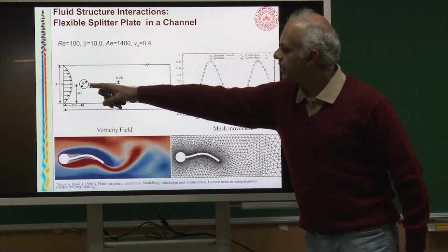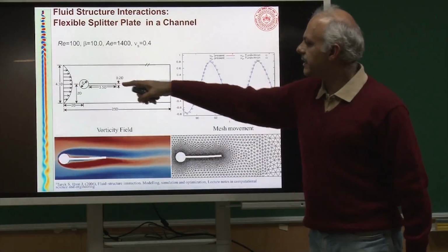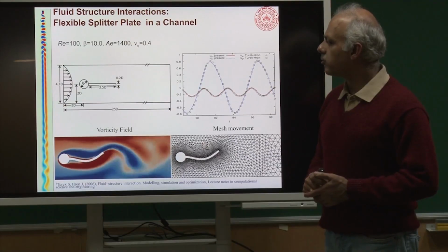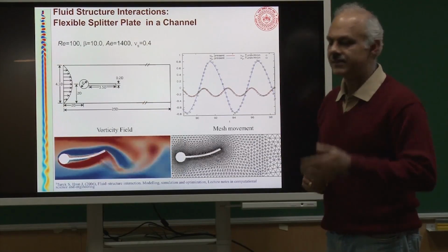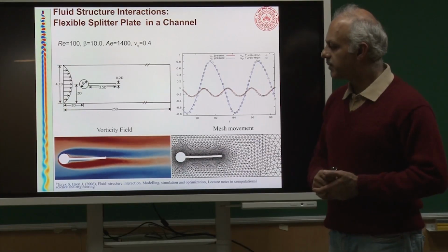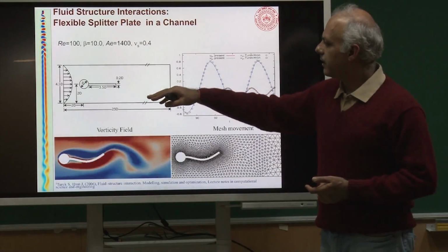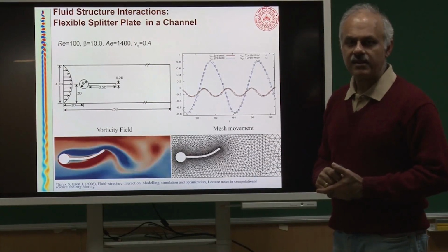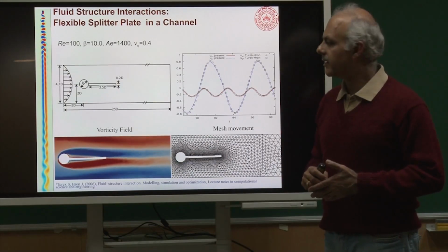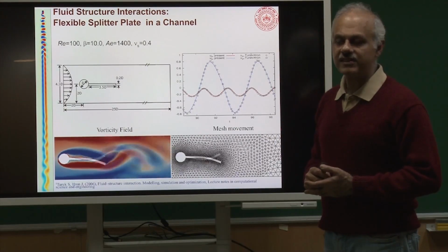There is a cylinder which generates an unsteady flow, and attached to it is some kind of a flexible plate, a filament, and then because of vortex shedding, this filament can vibrate. Okay. And this picture actually shows you how this is being handled computationally. So, you can see the challenges here. The geometry is changing, but not in a prescribed manner, that is part of the solution. Okay. So, there is a very tight coupling between the flow and the structure.